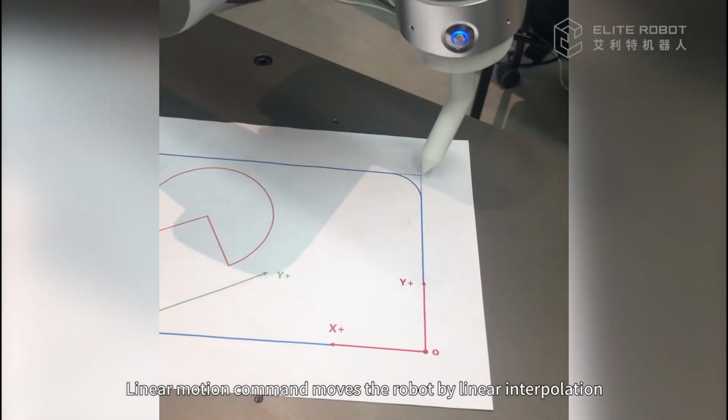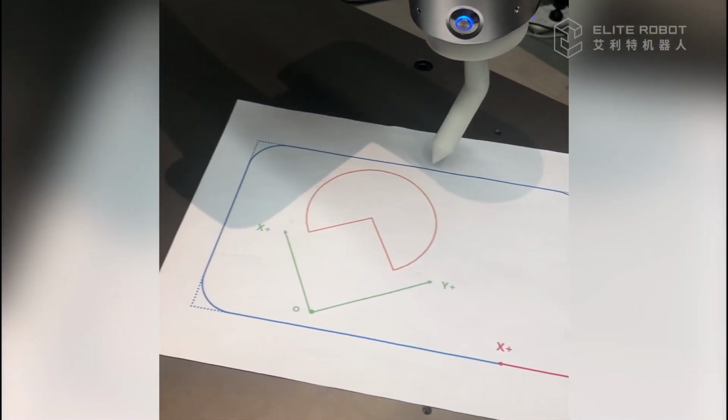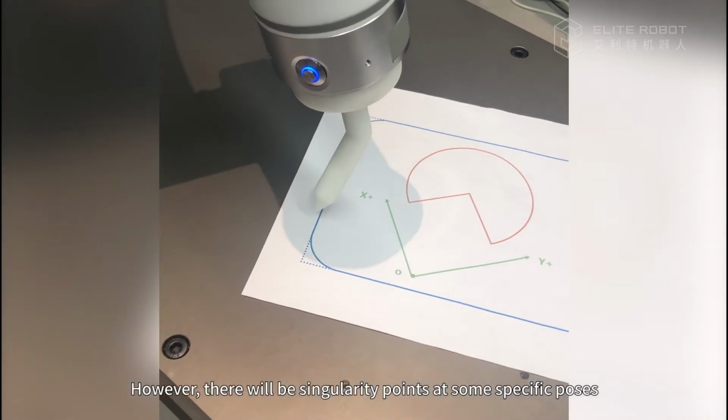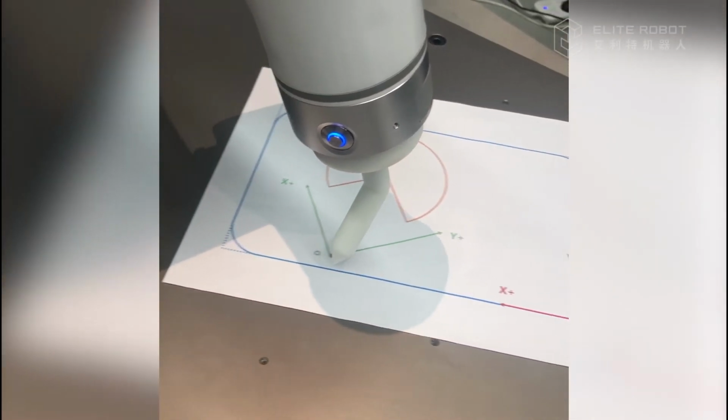Linear motion commands move the robot by linear interpolation. The trajectory is easily predictable. However, there will be singularity points at some specific poses.